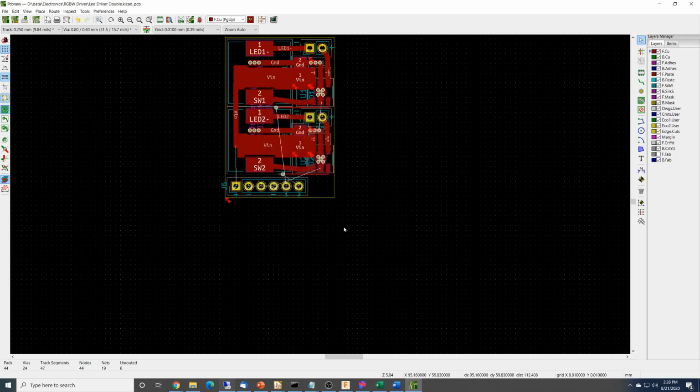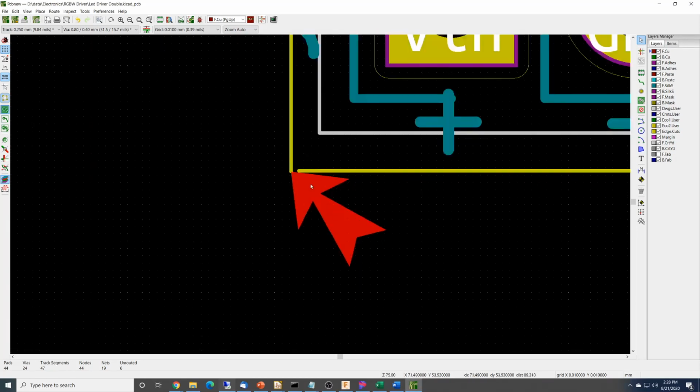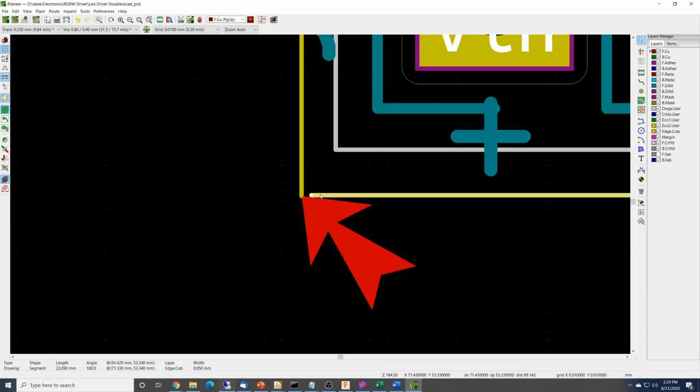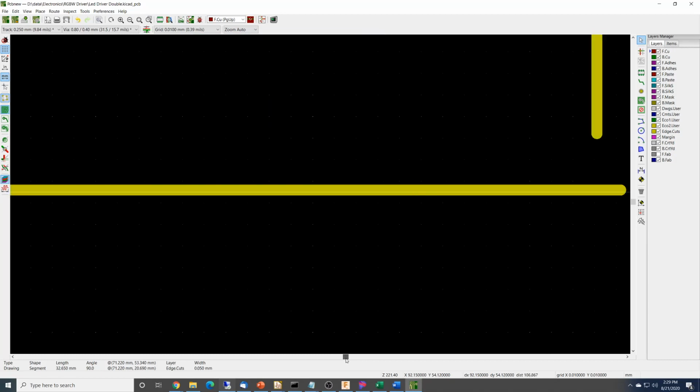Basically that's because I did not move things exactly. And here if we look at it, well, that's really obvious. So the simplest thing to do is zoom way in, and once again, hold down Control. Get that so that it's aligned, and then this one's a little off. Just adjust. You get the circles when they're totally in alignment.